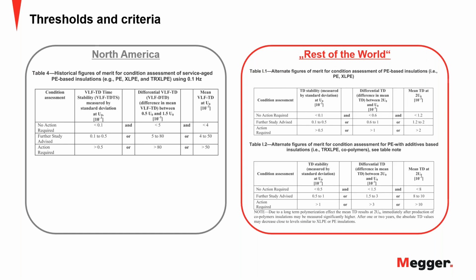This question has quite a few implications to it, if I understand it right. But we're really talking about two different tests, where you're looking at the cable and trying to determine different things. The tan delta test is basically telling you what's the remaining dielectric strength of the insulation. So it's a global test. Whereas with PD, we're looking for a defect at a specific location.